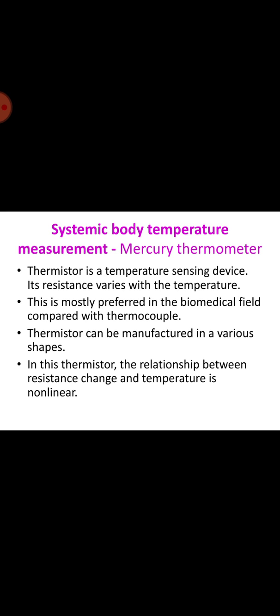Thermistors are made up of metallic oxides, binders, and stabilizers pressed into wafers, then cut into chip size and left in disc form or made in another shape. There are many shapes available for thermistors. The precise ratio of the composite materials governs the resistance-temperature curve. Thermistors, derived from the term thermally sensitive resistors, are very accurate and cost-effective sensors for measuring temperature. Thermistors are available in two types: the negative temperature coefficient and the positive temperature coefficient.